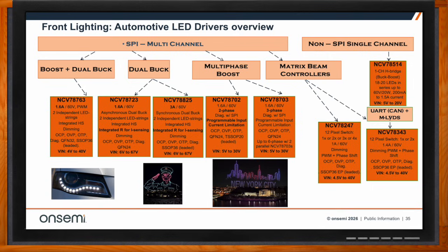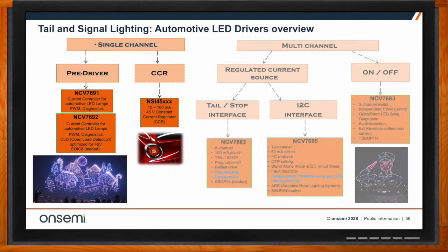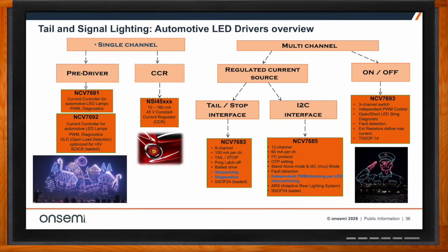You might have a fully charged battery, and by the time you're done with your 20-minute flight time, it's down to 10%. So that voltage is changing. So you want your electronics to be happy with that. You don't have to add DC to DCs. And these can literally run directly right off the battery packs. Anytime you do that, it's more efficient. So we've got the front lighting, and the next slide, we have the rear lighting, which just has more capabilities.